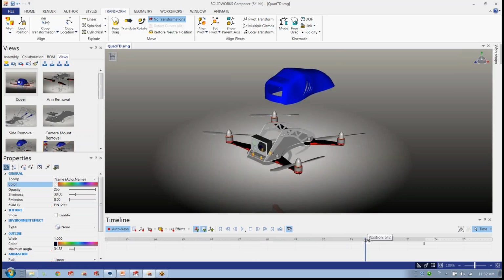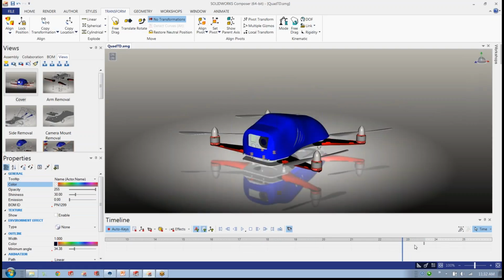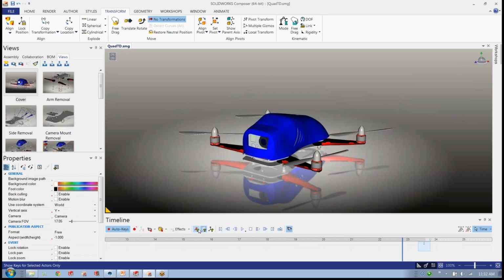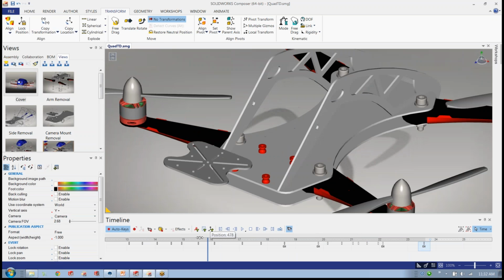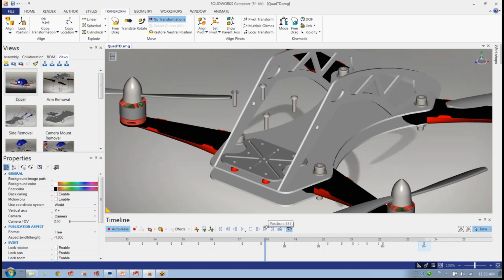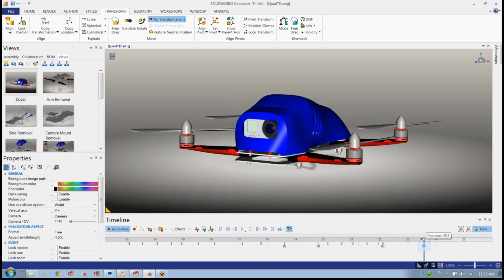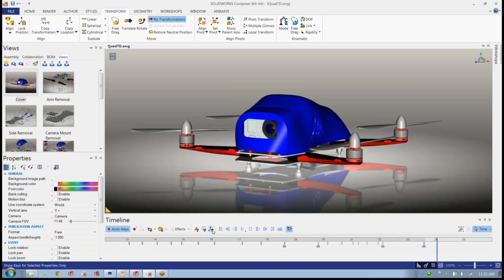Let's browse down to the end of our animation. You can see that right at about 23.5 seconds we have a key that changes the color for those selected actors. Let's go ahead and delete it. By deleting that key, we've actually told the animation to keep that same red color for all 4 of those bushings throughout the rest of the animation. So that allows me to get exactly the behavior that I want.